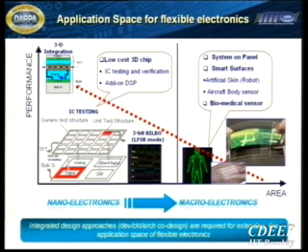So now, if I really think of using it along with standard CMOS circuits, then I have to face several different kinds of problems. The problems that turn out to be important are that I have to have CMOS compatible operation. I can't possibly use a 15 volt VDD for those devices. And second, the devices have to be really small. Certainly I'm never going to have the performance that I would have with my bulk silicon CMOS technology. But here I'd like to get reasonable performance.